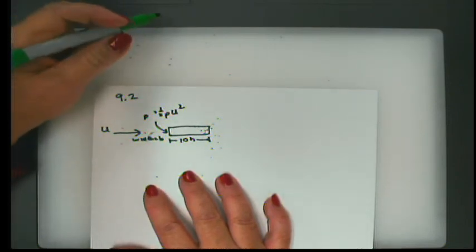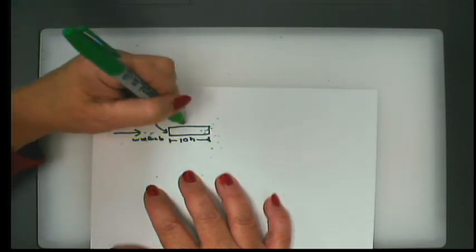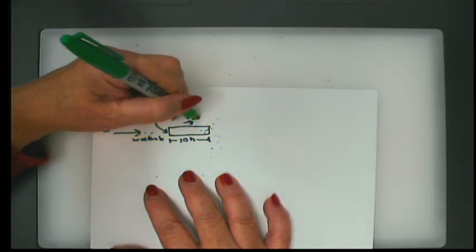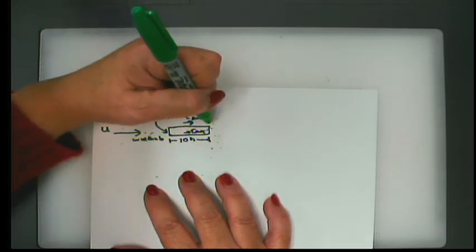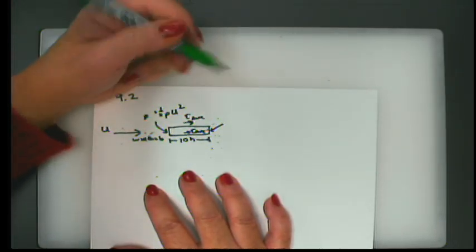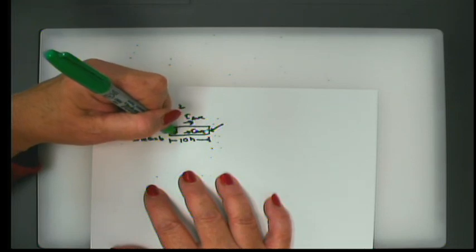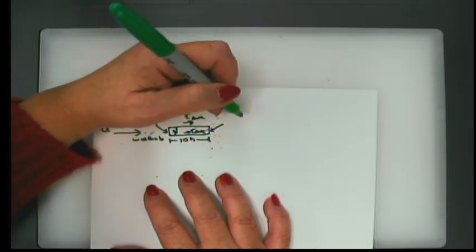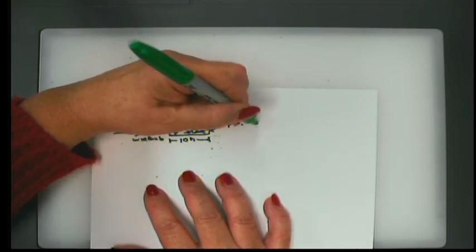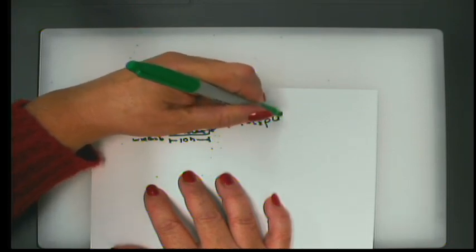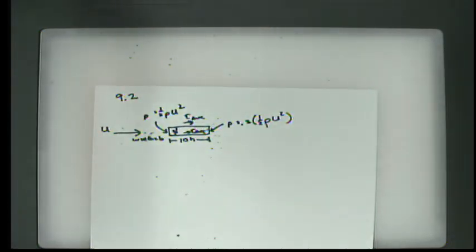So it looks rather familiar. We have some sort of a tau average on the top, some sort of a tau average on the bottom, and we have pressure. Also, this has a height of h. We have a pressure on the back end of 0.2 times that same quantity. All right, so the question is, the pressure on the ends of the bars are shown, and the average shearing stress on the top and bottom are tau average.